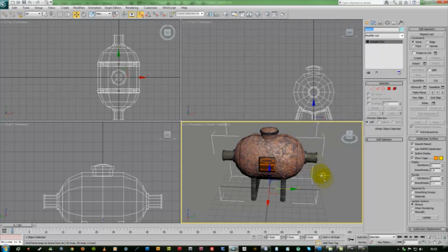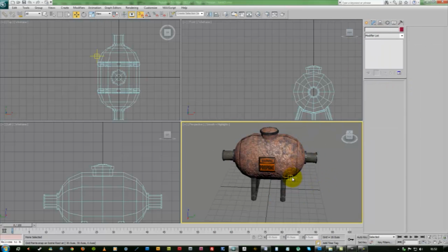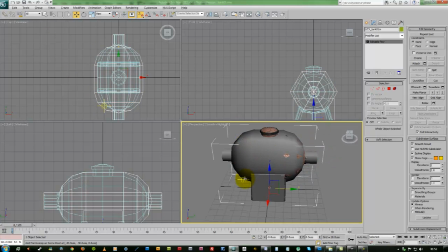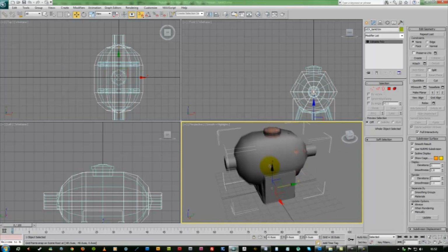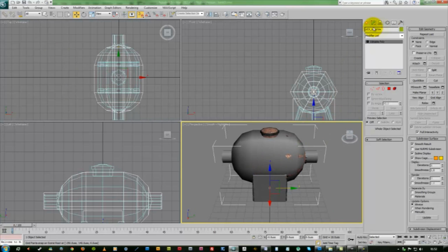so we'll copy that, and we'll now unhide the collision mesh which was created earlier. So we unhide all, and here's our mesh. As you can see, it covers the entire original mesh, not allowing a player to be able to run through it at all. So if we take that and we go UCX underscore, and we'll just paste back in the name of Tank01.